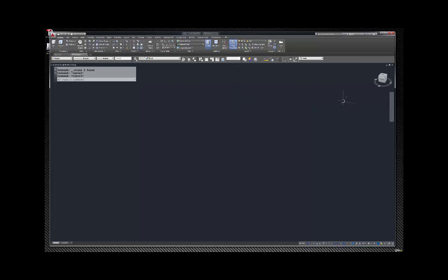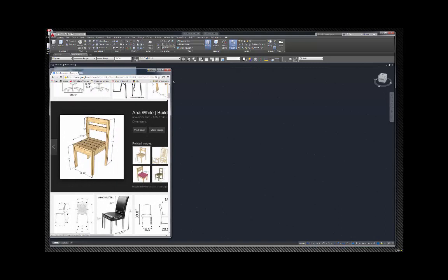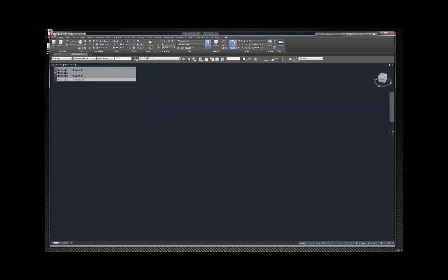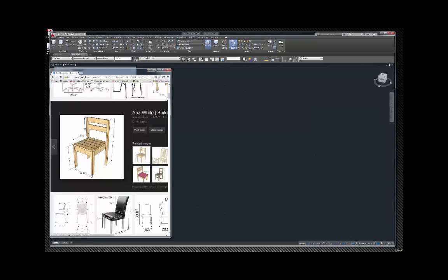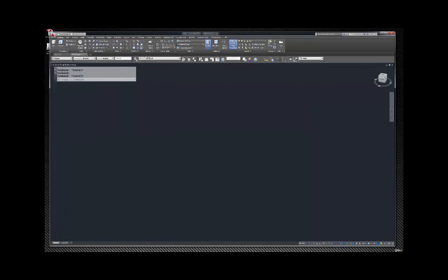And here we are, and I have my dynamic input off, and I'm going to right click, make sure I'm in parallel, set that as current. Right down here, there's my UCS with my world. So I'm good, and here's my command line, so I'm ready to go. I'm going to look at this little drawing. Maybe I can just park it over here.